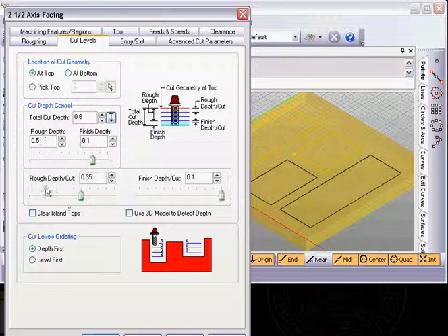And for roughing depth of cut, remember, I don't want it to go over one diameter of the tool in most cases, so I'm going to set 250 thousandths here, since it's a 1/4" cutter. And then the last cut is going to be made at 100 thousandths, which will make the tool not stress as much, and so it'll give a nice finish to those.